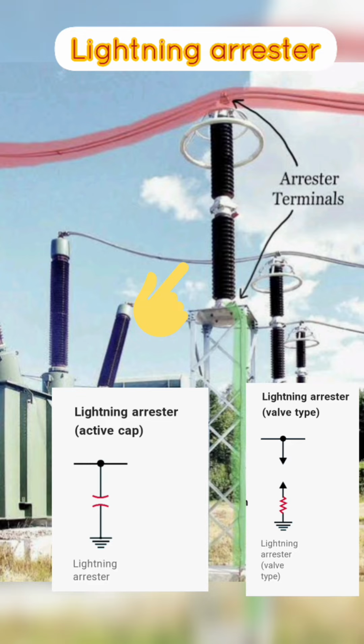In addition to the basic lightning arrestor symbol, there are also variations that indicate the specific type of lightning arrestor being used. For example, a symbol with a circle or diamond inside the zigzag line may indicate a metal oxide varistor, MOV, lightning arrestor, while a symbol with a line connecting two zigzag lines may represent a distribution class lightning arrestor. Symbols may also be used to indicate the location of lightning arrestors within the substation.